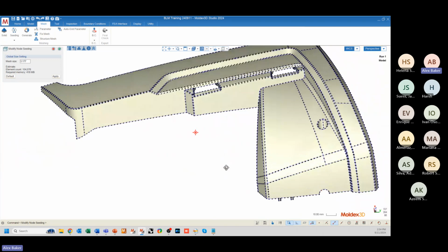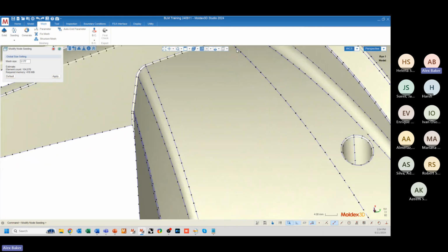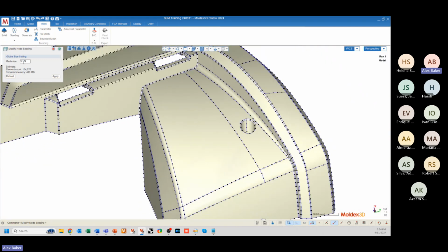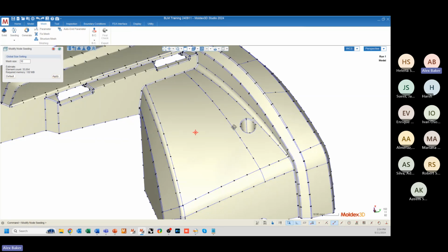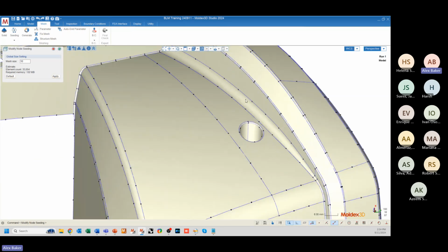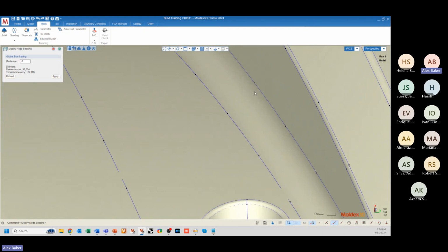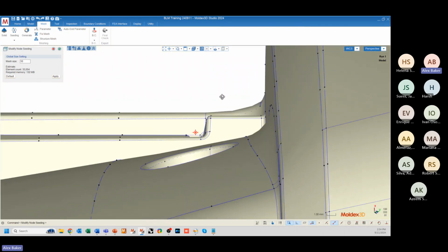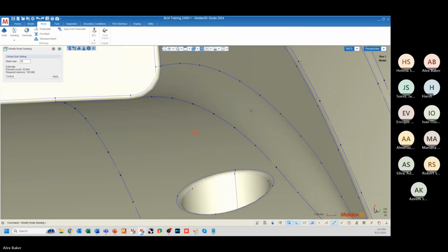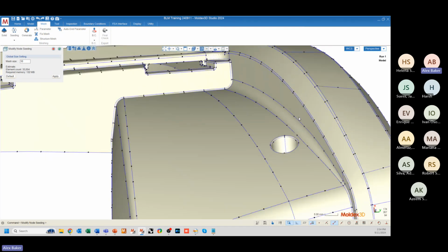And this carries into some of the more generic features on our geometry, especially as we start to increase unreasonably, let's say even up to a mesh size of 10. You can start to see how some of these geometries, like this big fillet here, is just going to have an element that goes from here to here, and it ignores that fillet contour completely.